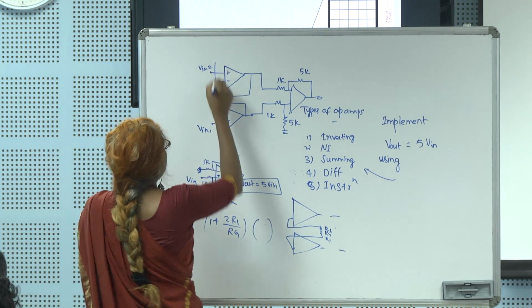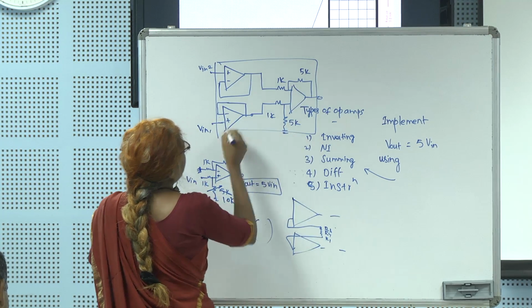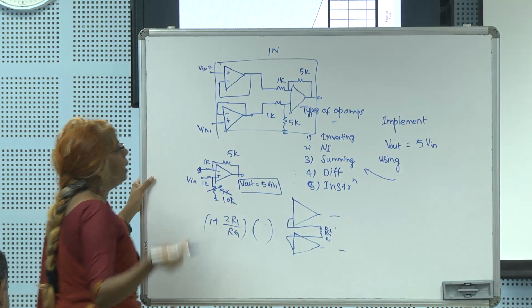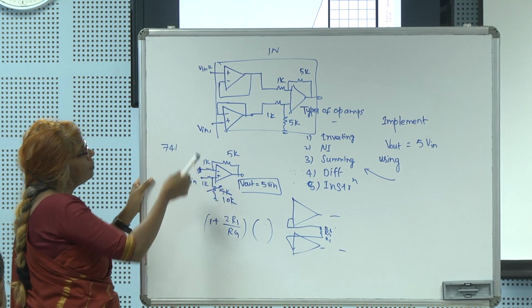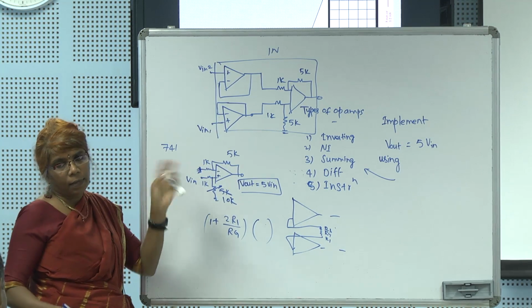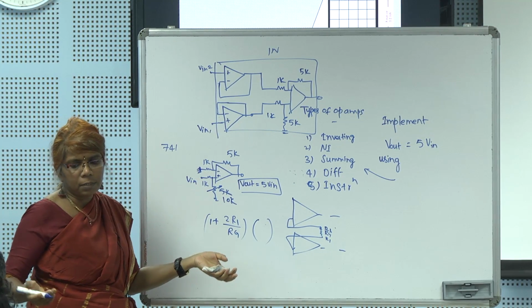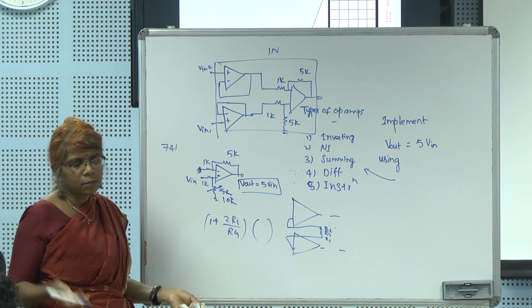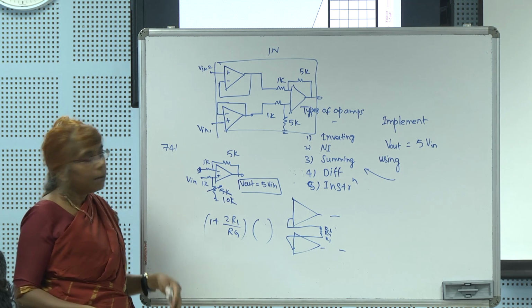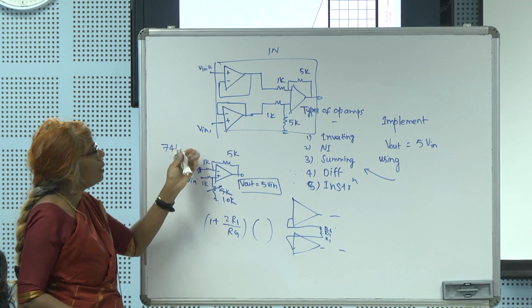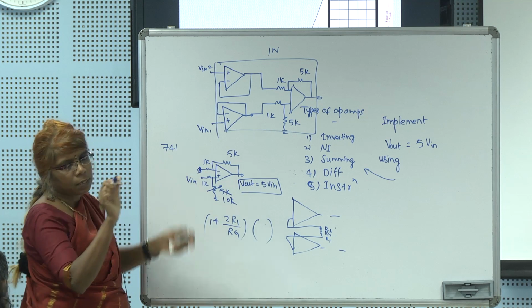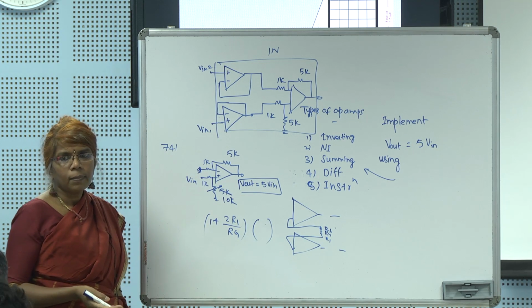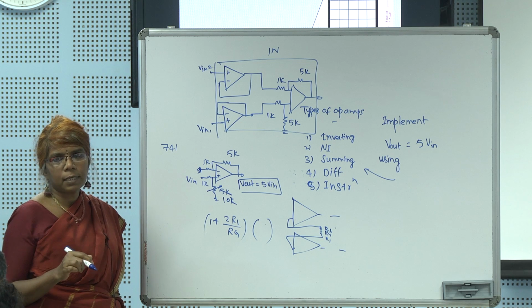We can buy this whole thing in one chip, but normally in many labs we get 741s, correct? So, we can use 3 of them. We build both ways, we got almost similar results. I tell the students do whatever you like, I do not restrict, but many people do this. Otherwise, you can buy one chip, it will have all that, you just give the input, adjust the RG and then you can go ahead. Is it clear what I am talking? Does it make sense? Questions?